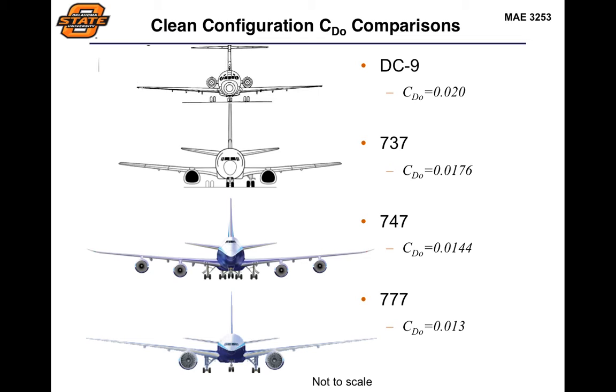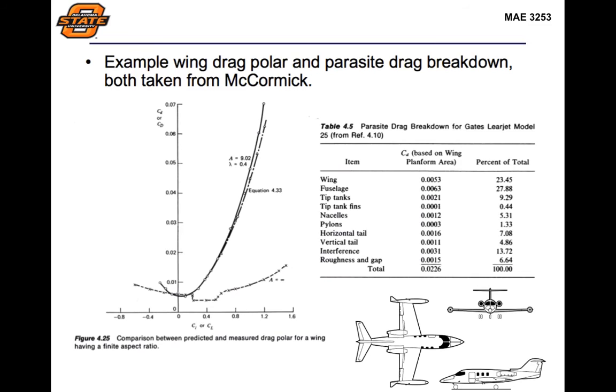So you really want to look for a 0.015 to 0.02 range for a reasonable estimate of what that CD naught is going to be. Now keep in mind that, again, this is the most difficult thing to predict on that aircraft, what that actual value is. So going back and looking at additional examples is very, very useful to do.